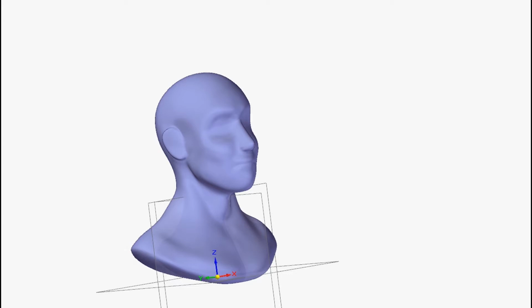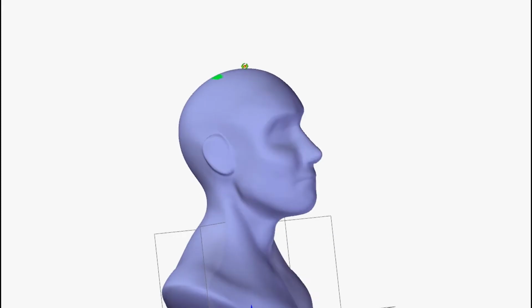And then you'd use the extract command, which would create surfaces for those regions. So it would create a flat surface on all the planar regions in that body, and so forth, and then you can trim and stitch all those surfaces together. The manual command here is basically to do what I just explained, but manually.